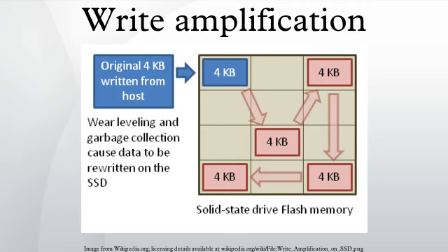Another solution is to have an efficient garbage collection system which can perform the necessary moves in parallel with the host writes. This solution is more effective in high-write environments where the SSD is rarely idle. The SandForce SSD controllers and the systems from Violin Memory have this capability.